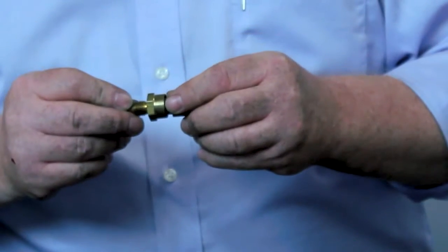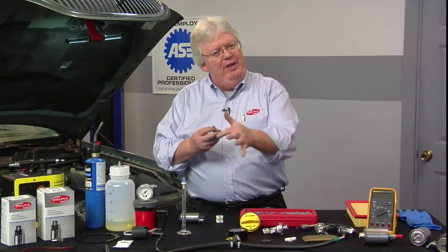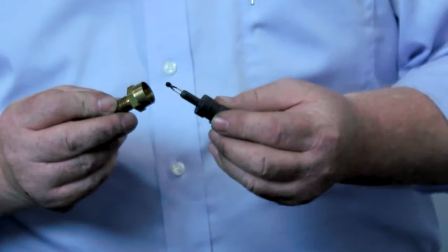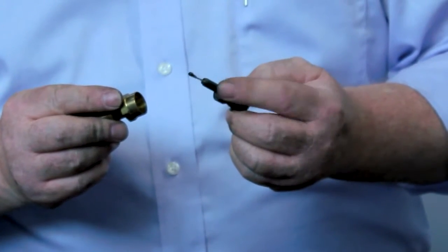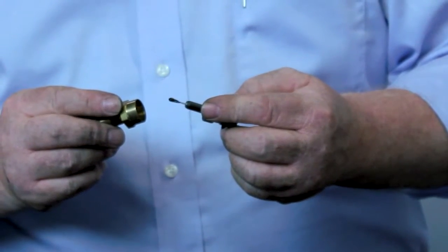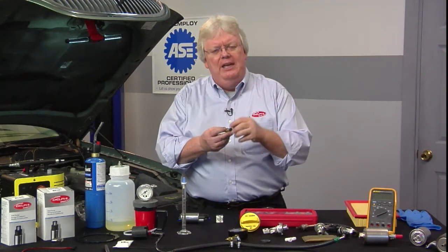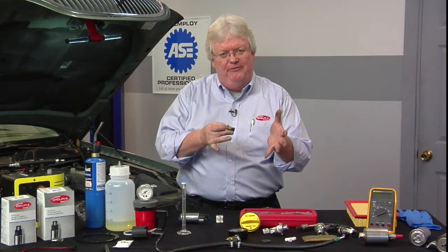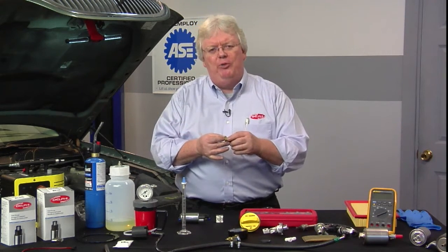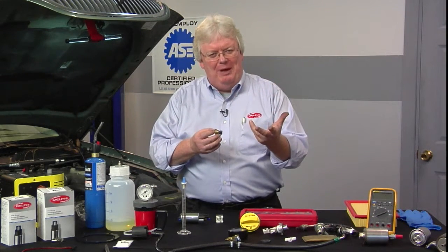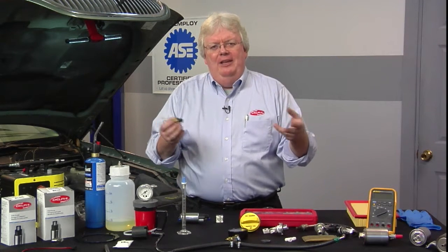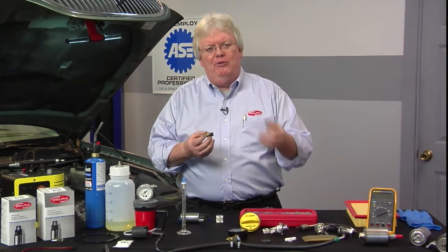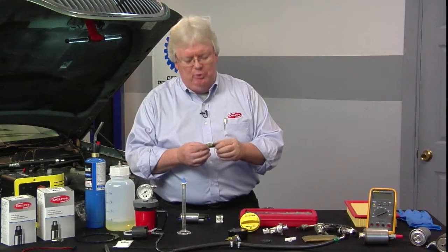And finally, looking at sensors. If the coolant sensor is shorted or open, we'll get a code for that. But if it's skewed, if the internal thermistor in the coolant sensor or intake air temp sensor is a little bit off, and if it's saying it's hotter than it really is, it will not spray as much fuel as it should during the base pulse width spray. The O2 sensor will respond by saying it's not got enough fuel. I got way too much O2 left over, and the positive fuel trim numbers will be the result.